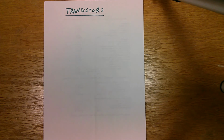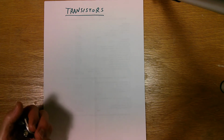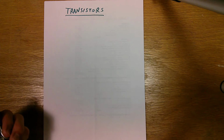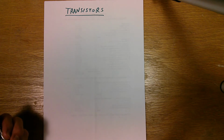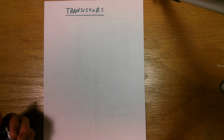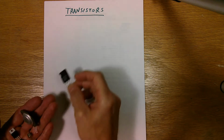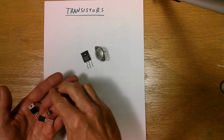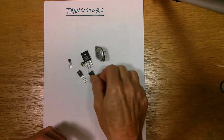In this tutorial, I want to talk about transistors and how to use them to interface to your microcontroller. Generally, they'll be used when you have a load or something you want to interface to that draws too much current or has too high a voltage for the Arduino or the microcontroller to drive. And transistors come in many different sizes and packages, and the bigger ones tend to dissipate more power, so they're used in heavier applications.